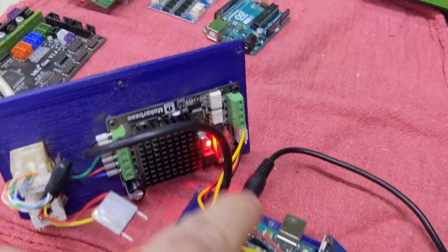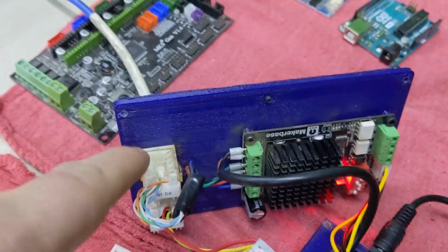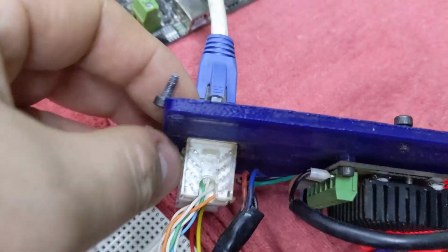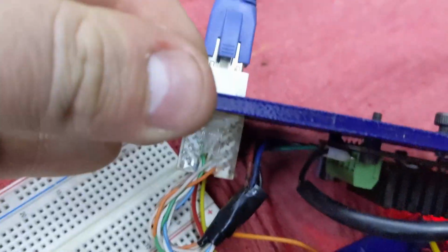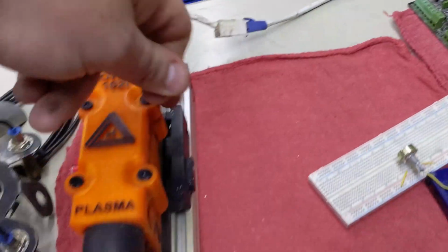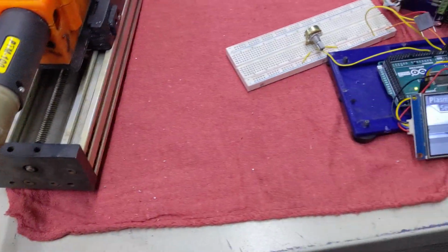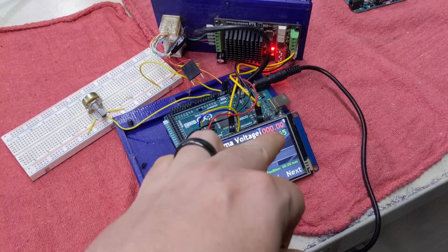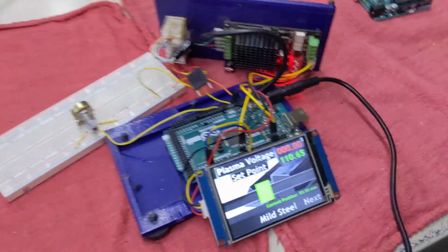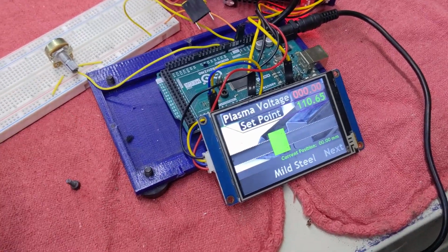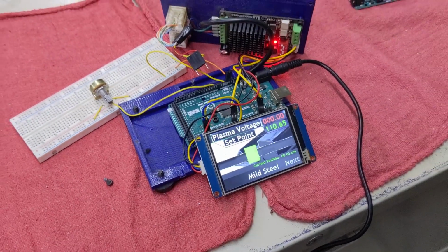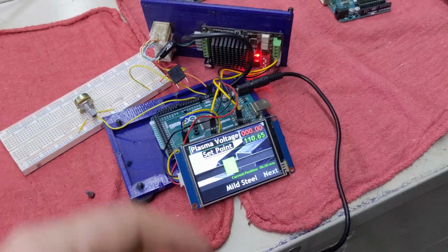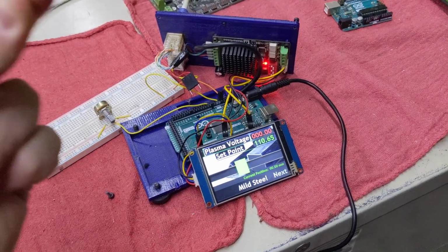So that's it. So up and down signals goes to driver, driver goes out to this line here, about to lose a screw, out here into the motor, and then up and down signals, and there's a feedback loop. The plasma cutter will deliver a different voltage depending on the height, and we're good to go. And that's how she works, man. So let's put her back together through the magic of video editing.